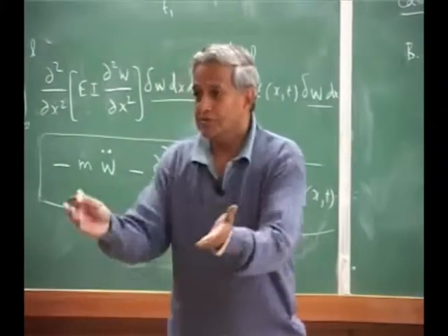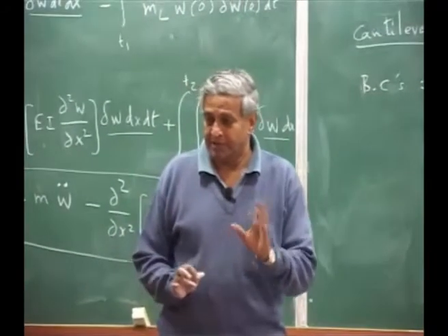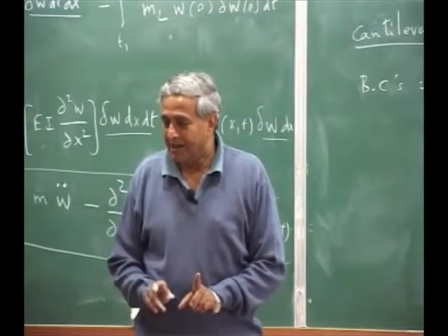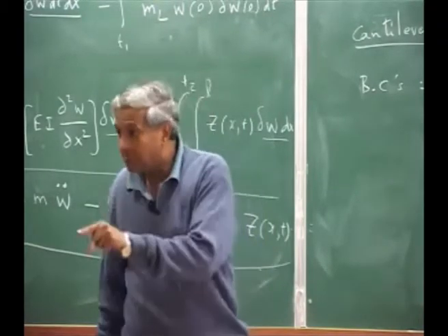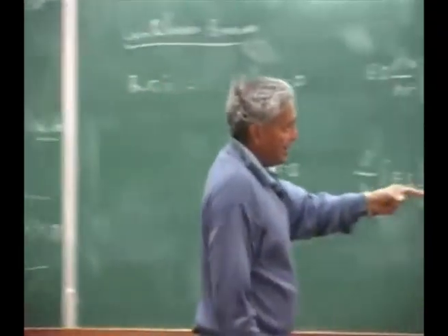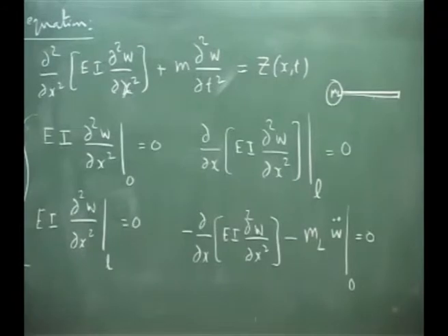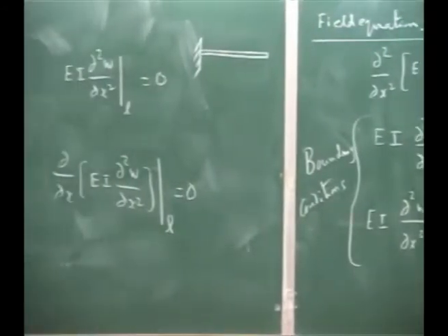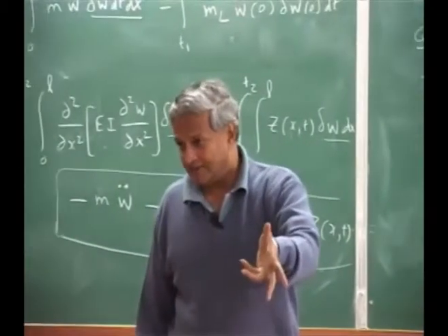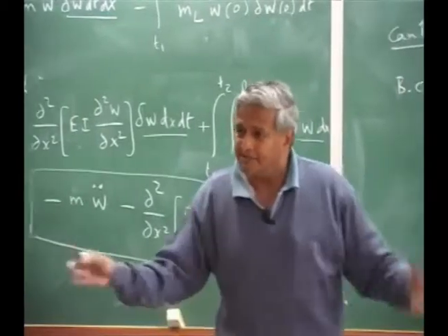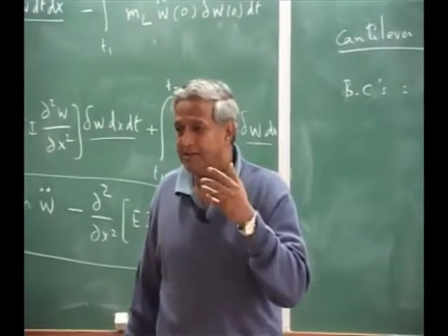Now the solution to the problem, that is where the next step is, because you obtained the equation. Please understand, Hamilton's principle will give you the equation which is valid for the field, and the beauty of this is it also gives you boundary conditions for the given problem. Why I choose this M here, one mass at one of the ends, is because later when I derive a very general principle for solution of this type of problems, if I put everything 0, you will find that I will not be able to bring out a generality. Whereas if I put a mass at any end, left end, right end, anywhere, I can give a general expression for one formulation. How do you get the solution for that?